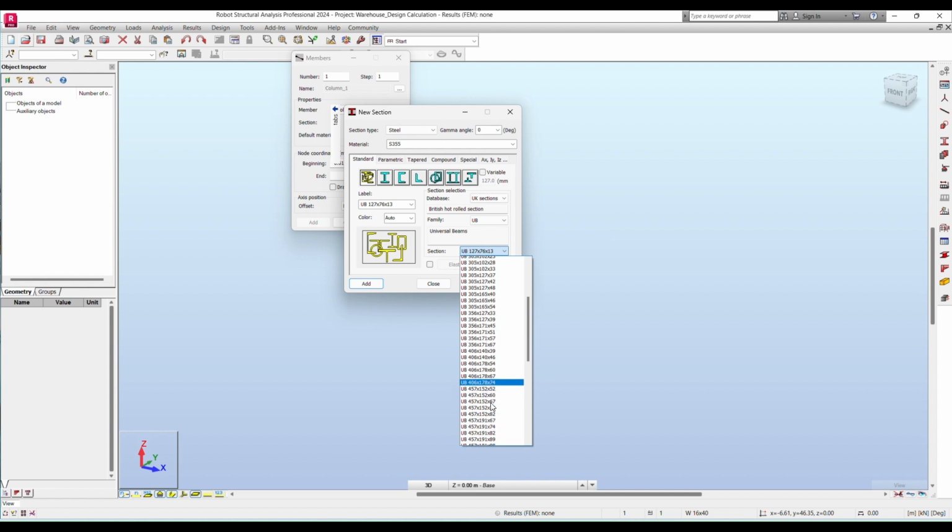So we need to have some deeper beams, and for that we are selecting the UB. Coming to the section profile, generally we can select height divided by 10 or 12 in the range of the sections, so that the depth can be safer. At present we can select 533 by 210 by 82. Here we are going to do an iteration method. If this 533 is okay with the optimized design, we are going to follow the same, or else we are going to reduce. If it is unsafe, we can increase it, or we can do some rearranging of the frames.